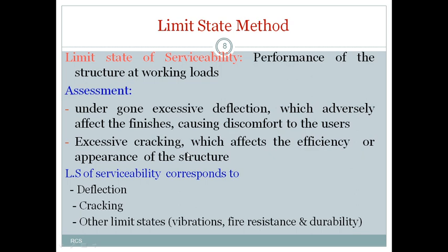Because the deflection will adversely affect the finishes. That means if any structure is subjected to deflection, then finishes like plastering may open up or fall. Then the inmates of that structure will feel discomfort.